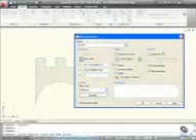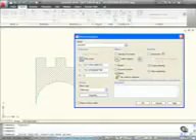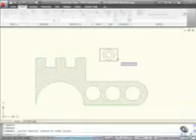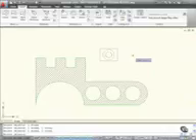So now I have to select the objects that make up my block. I've got three options. I can delete the originals, convert the originals to a block, or retain the original objects. I'm going to utilize delete, and you'll see why in a moment. Select objects now by clicking here. I select the objects: rectangle, circle, circle. Notice I picked on all three of those. I could, if I wanted to, left click and drag, do a crossing selection.